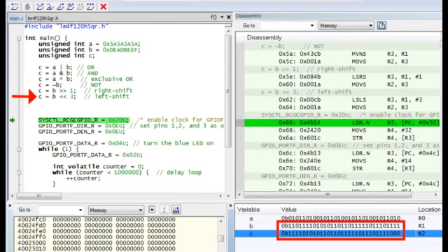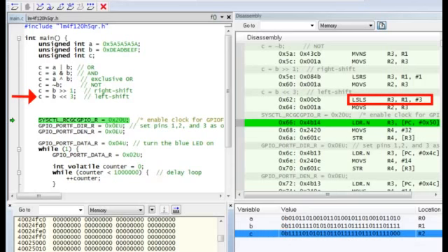But you need to be careful because for a large first operand, like in this case, some of the most significant bits might fall off the left edge, which simply means that the result after the shift no longer fits in the 32 bits. In the disassembly window, you can see that the left shifting is performed by the LSLS instruction. Please note that the LSLS instruction shifts zeros into the least significant bit position.